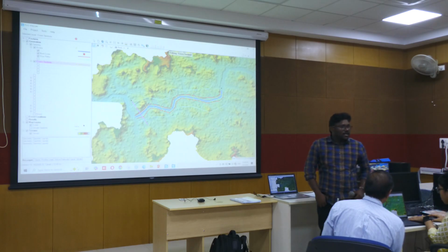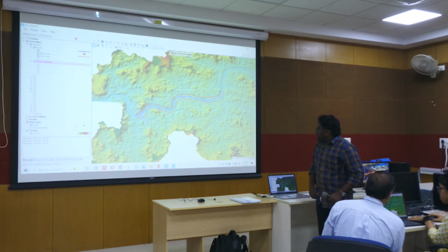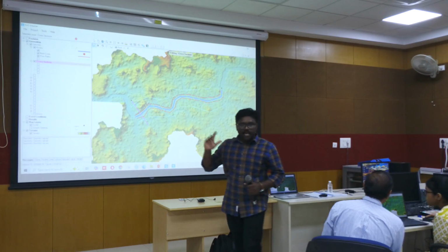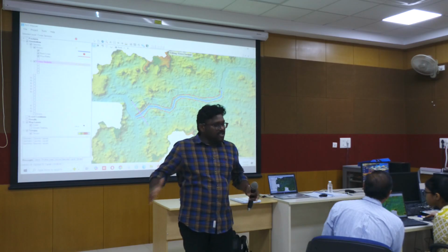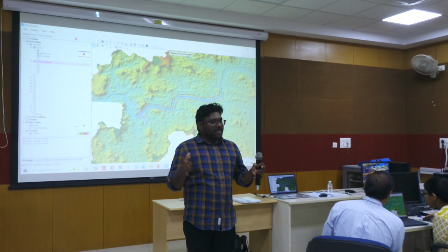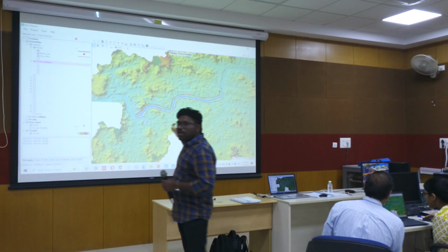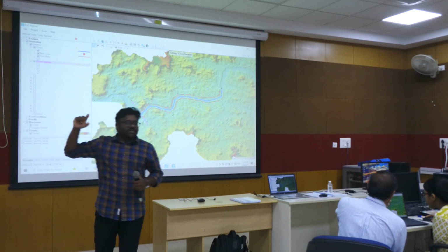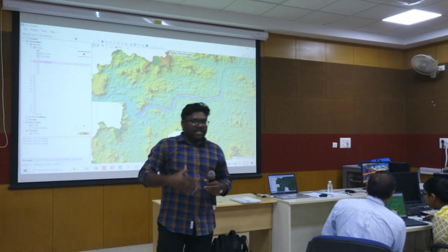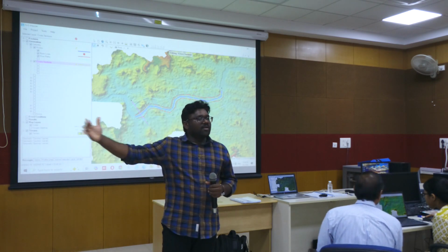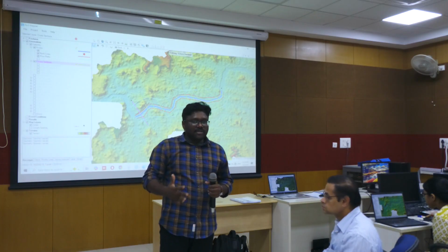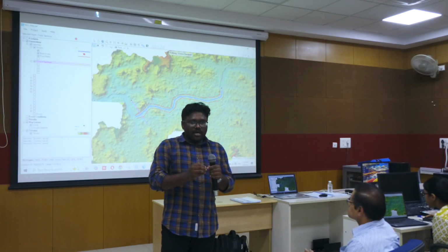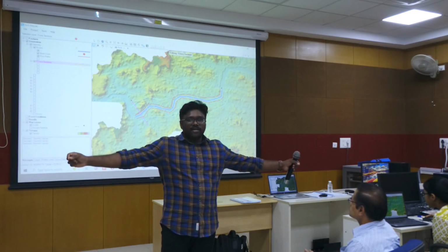Understood? That cross section will give you the shape of the river. We will assume that depending upon the cross sections only, the water will flow and can't go beyond these lines. So after getting results, you will get to know that even if the inundation is out of the cross section, it won't show you. That's why when you are drawing the cross sections, you have to try to cover the possible area of the flood. Okay?